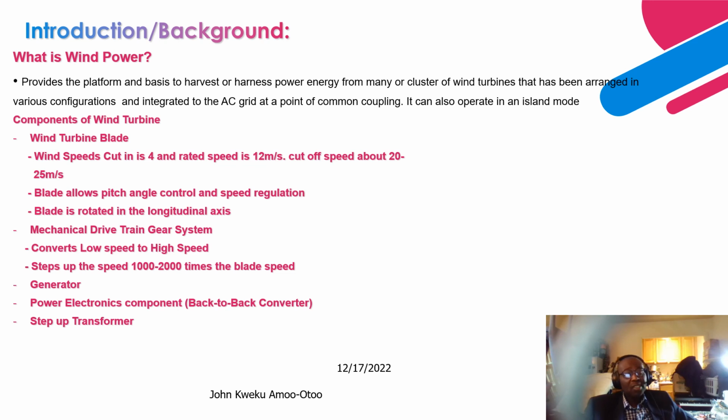So, this applies to two different types of wind turbines. And what are they? The doubly-fed induction generator, which utilizes a 30% power rating back-to-back converter. And the permanent magnet synchronous generator, which utilizes a full scale, 100% power back-to-back converter.